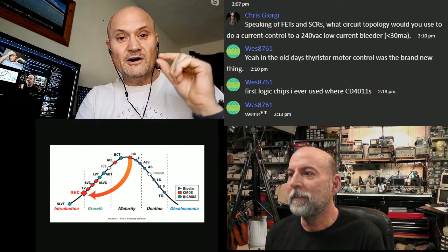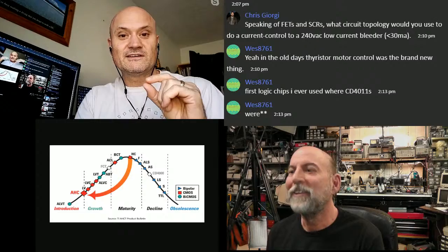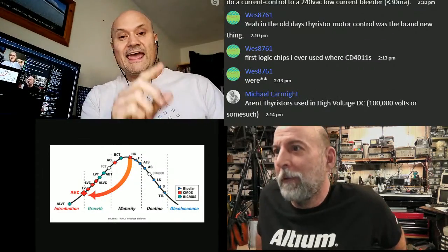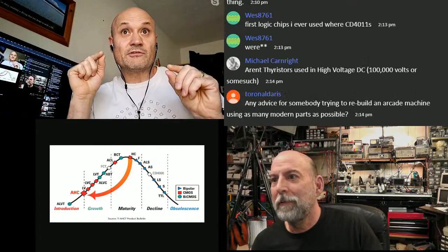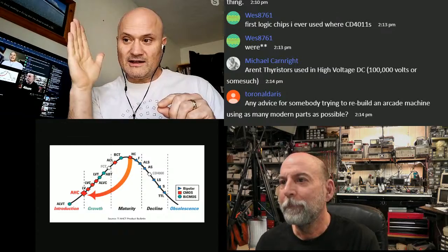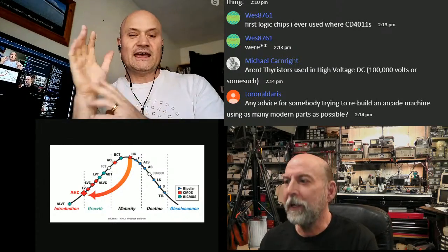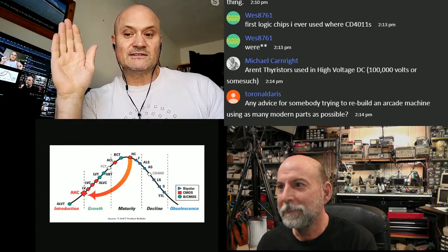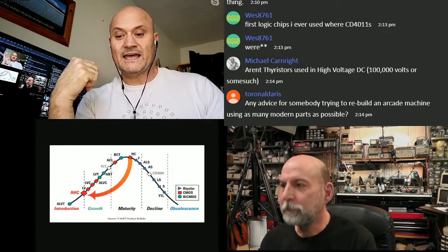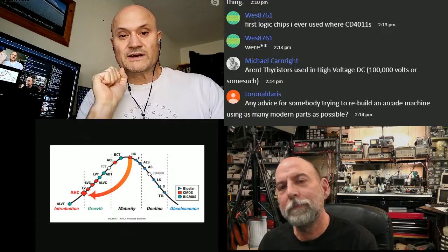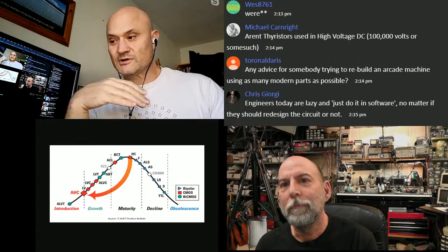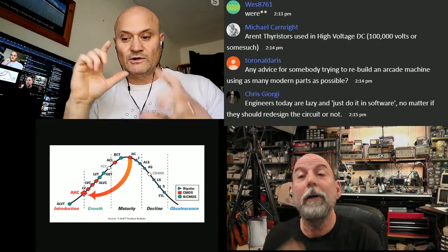And they have sample and hold. They used the 4066 as a quad bilateral switch. Yeah, that's a second form of the quad. And that goes into an LM311 high-speed comparator. And they have a 12-bit R2R ladder for D/A, and a custom ASIC that took care of the successive approximation process. And it took care of storing the audio data stream into a DRAM bank and took care of DRAM refresh, all in one big custom ASIC.